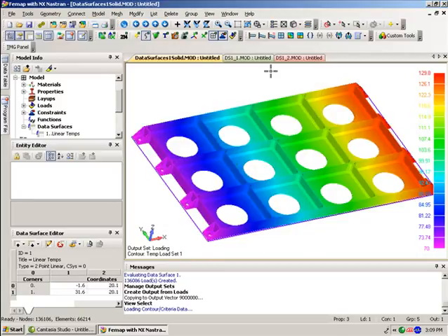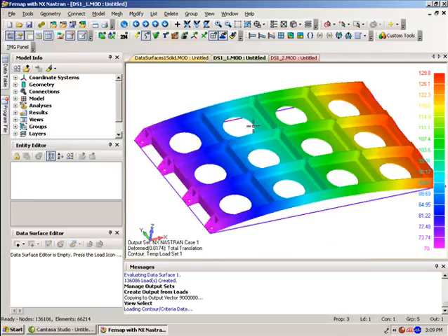And what we did now, I've already run these. So here's this model run, and there's actually some support beams underneath this structure that's applying stiffness in this direction. But then if we load that up, we'll see we get a maximum displacement of 0.0174.